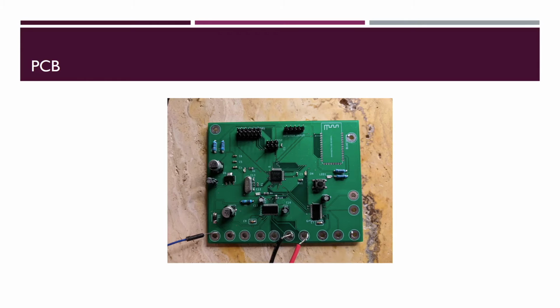The several pins along the top are for connecting our sensors and joysticks. In our final product, these pins will be removed, and the wires will be soldered directly to the board to prevent them from separating when the car is in use. One design change we may consider in the future is moving the components closer together and reducing the overall size of the board. The components were spaced out like this to make soldering the small surface mount devices easier, but currently it's not needed.